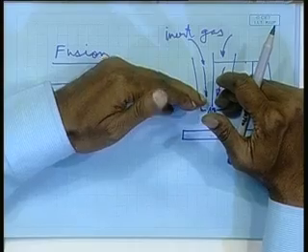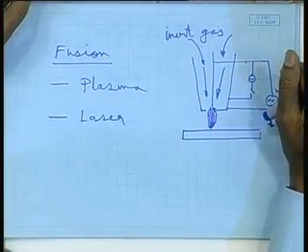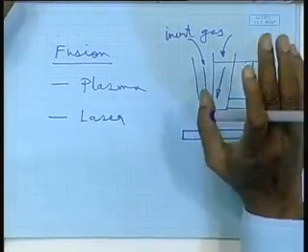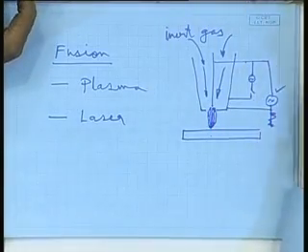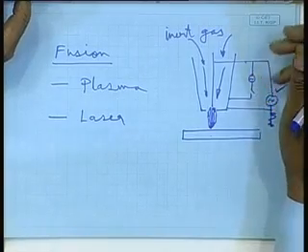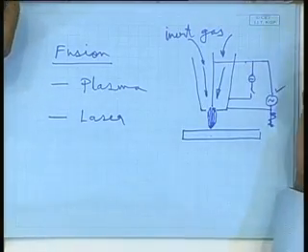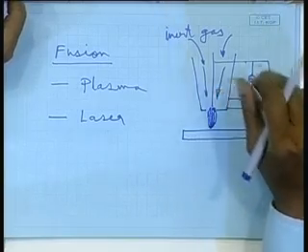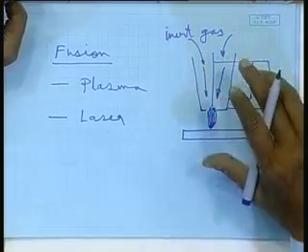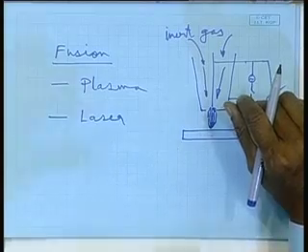With plasma cutting you will have very high productivity because of the highly intense source of heat. You can use very high speed cutting. Now, if your downstream activities are not of that high speed, then investing in this and having a very high productivity cutting process won't make much sense. That is a different issue, but otherwise it will give you very high productivity, as well as the advantage of cutting not only steel, but also aluminum. Anything can be cut, right. So, in simple words, that is the way plasma cutting is done and the advantages of this.